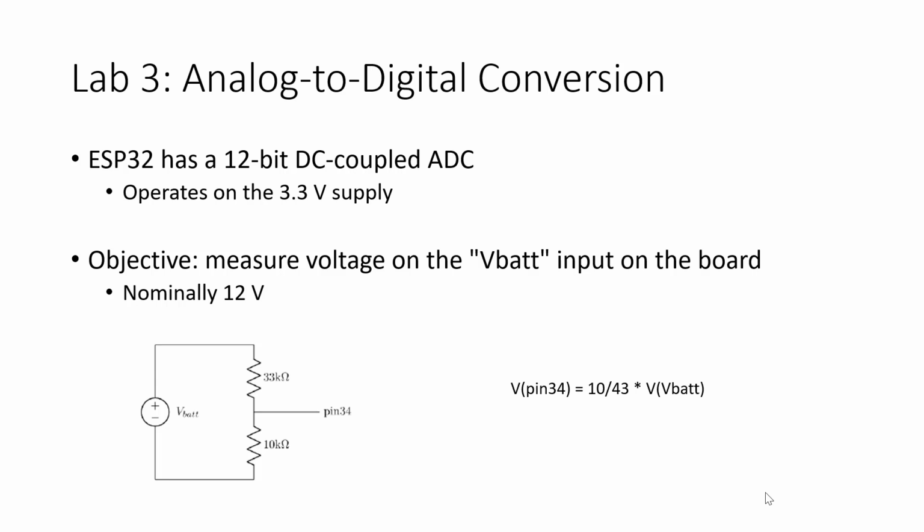So make sure that you clip to the VBAT. The VBAT is the high voltage, and the 5 volt is the 5 volt voltage, and the ground is shared by both. Both power supplies share the same ground. They're both coupled through their ground, okay?